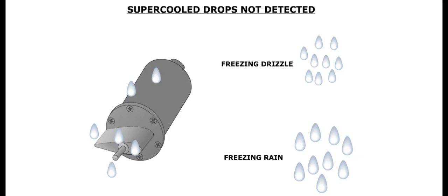Note: the detection system may not reliably detect large supercooled drops that are near freezing, since there may not be enough heat transfer to freeze the large water drops that contact the probe. This would typically occur with freezing drizzle or freezing rain.